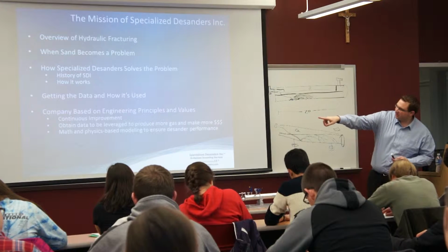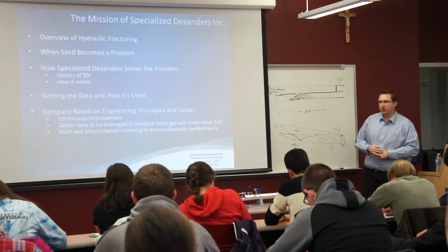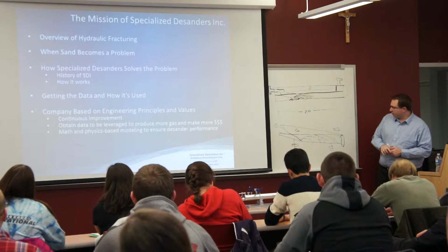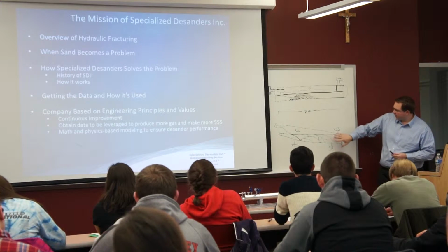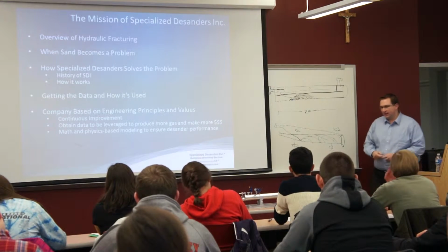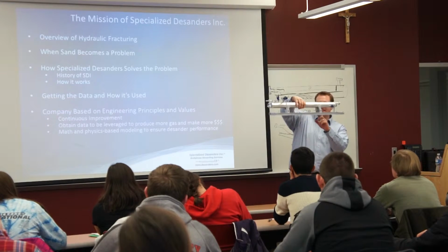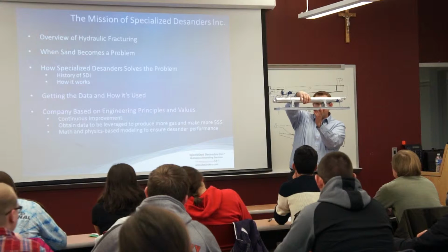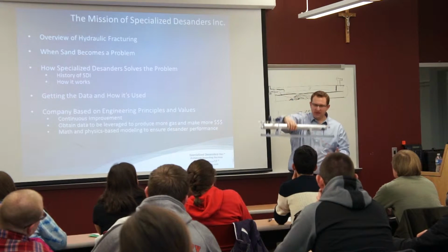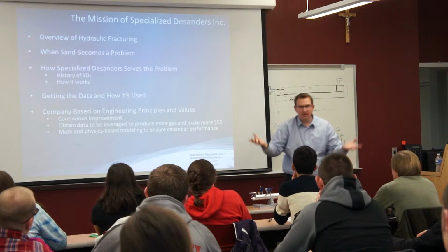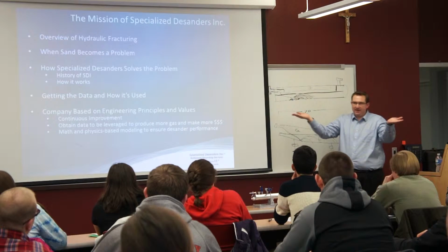But in that application of the verticals, you're blind. You don't know what's going on. What we started doing is putting this entire vessel on load cells. So we would jack it up off of this skid here, off of this metal base. We would screw up load cells, and now this entire vessel is being weighed at all times.